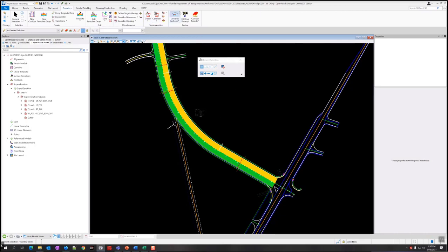Let's go to the Calculate Super Elevation tool. We're going over here in the Corridors tab, and under the Super Elevation section, the middle button is Calculate. Just to check, click the drop down to make sure you get the right tool. Calculate Super Elevation is the first tool on the list, so we're just going to select that. We're at exercise 3.10 here.